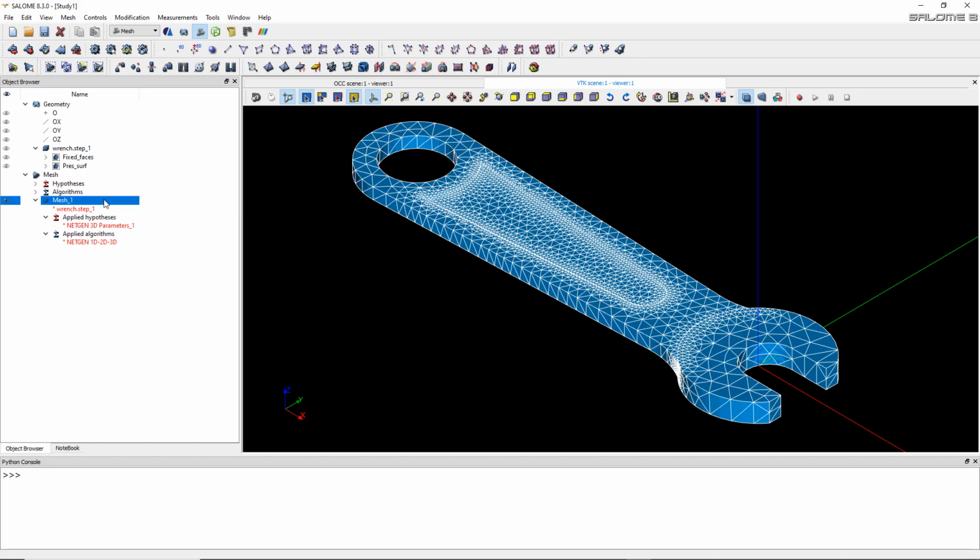Okay, so once I'm good with all of that, I will generate the mesh groups. I have those two geometry groups here. I need to get the same, but for the mesh, because what the Code Aster solver reads is ultimately the mesh groups, not the geometry groups.